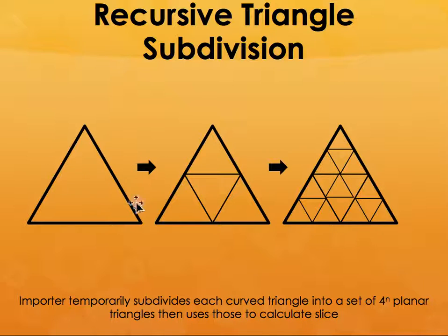So in order to increase the accuracy, what do you do? You have to increase the number of rectangles, triangles. If you want more accuracy, you go to even further subdivision of the triangles. But the more triangles, the higher the size of your file.